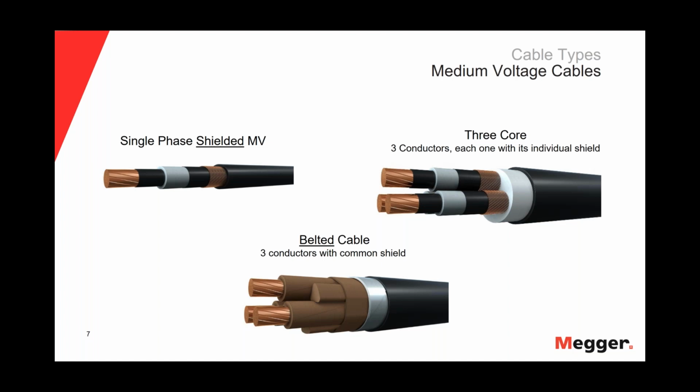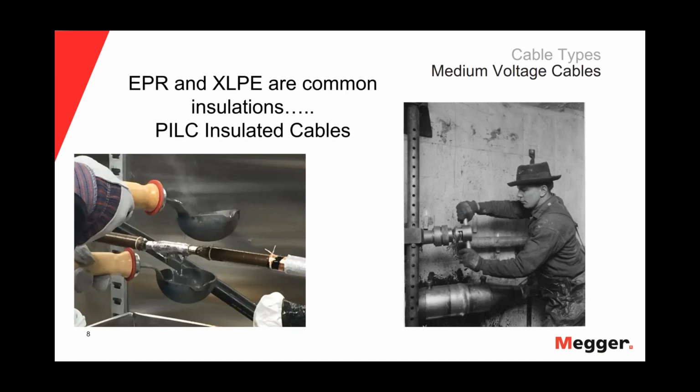As mentioned, EPR and XLPE are common insulations that we see today, but there's still quite a bit of paper lead insulated cables out there. The reason I highlight that with these 2 pictures is these cables have been around for a long time. They're still out there, and they do require some different techniques and troubleshooting applications versus the solid dielectric extruded cables.